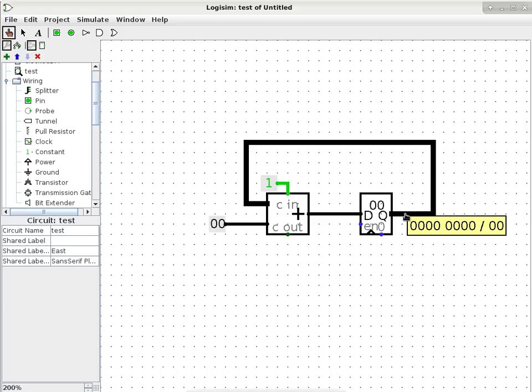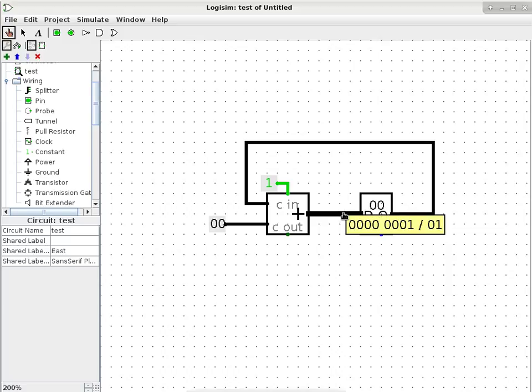The adder is always working. In other words, it's outputting a 1 already. But nothing is happening at this point because the register says, by default, I'm not paying attention. Okay, so if that is not paying attention, let's see what we can do with the register.